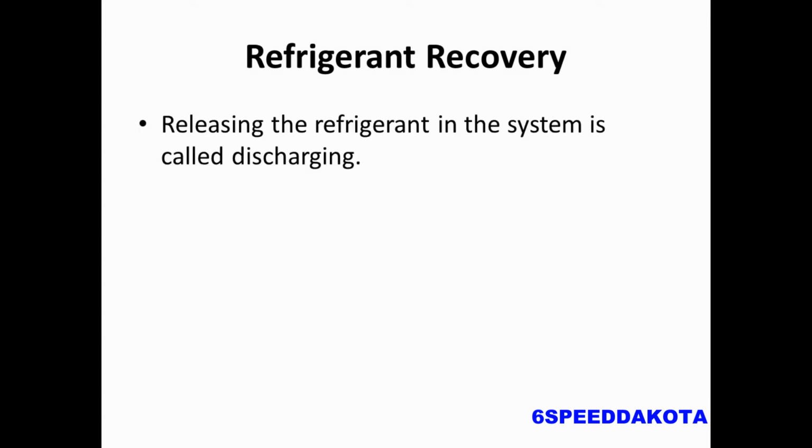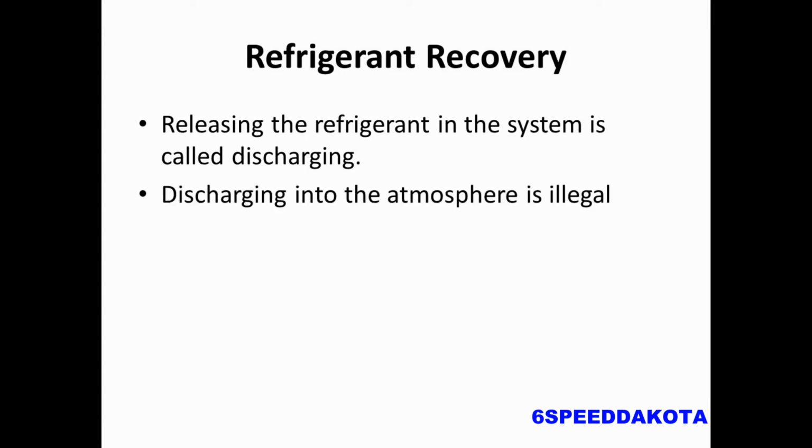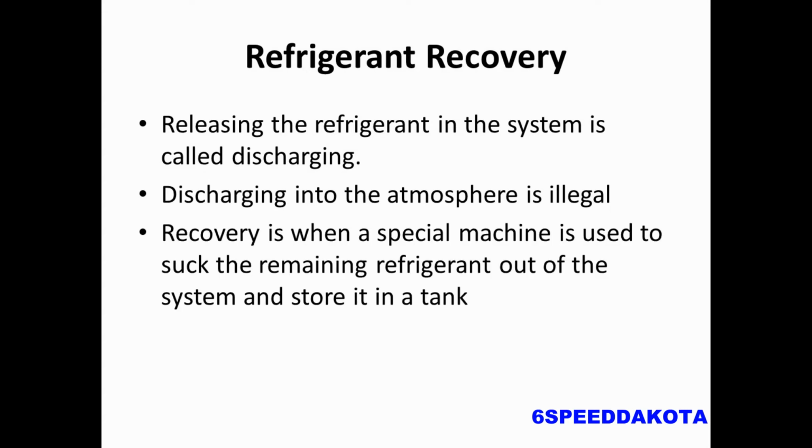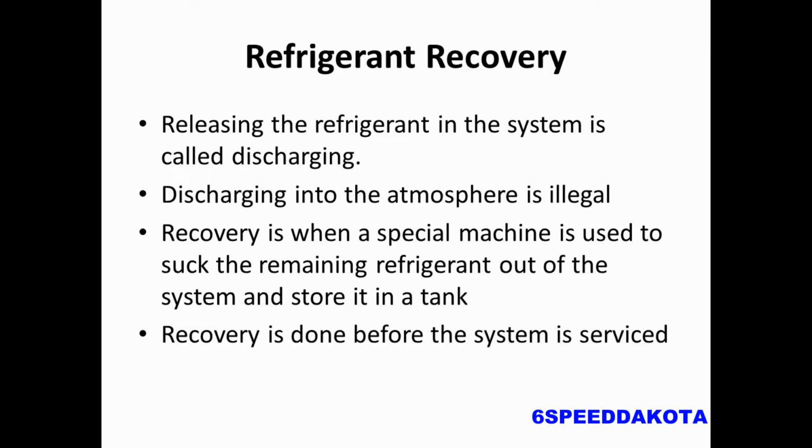So refrigerant recovery is kind of our first step. Releasing the refrigerant in the system into the atmosphere is called discharging. And discharging into the atmosphere is very illegal. So recovery is when a special machine is used that sucks the remaining refrigerant out of the system and stores it in a tank. So recovery is done before the system is serviced. You can't really service the system while it's under pressure.